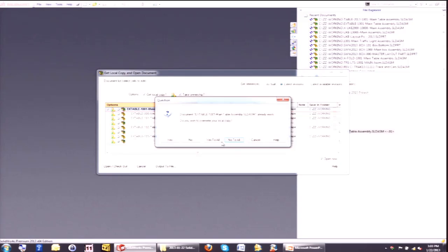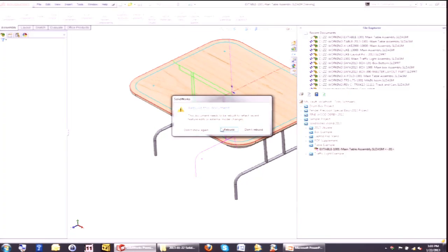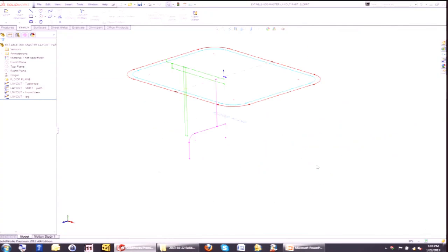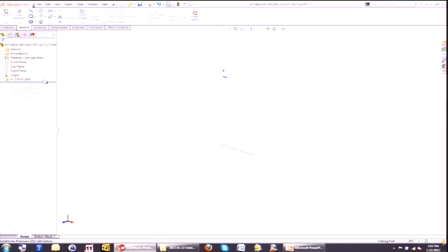So in this example here, like I mentioned in the introduction, the method is one that is defined by taking a single part file and drawing in some skeleton sketches. These are 2D sketches. You could certainly use 3D sketches, but I wanted to get the point across that that's not a necessity. The 2D sketches can be used to drive all the geometry in your model. So in this example, what I did was I started out with a floor plane, and then I indicated the height of the table, floor plane, height of the table will kind of work together, and the outside perimeter of the table. And then I created a sketch that represents a skirt that kind of sticks down, made of a different material, helps to strengthen the table, reinforce the table.